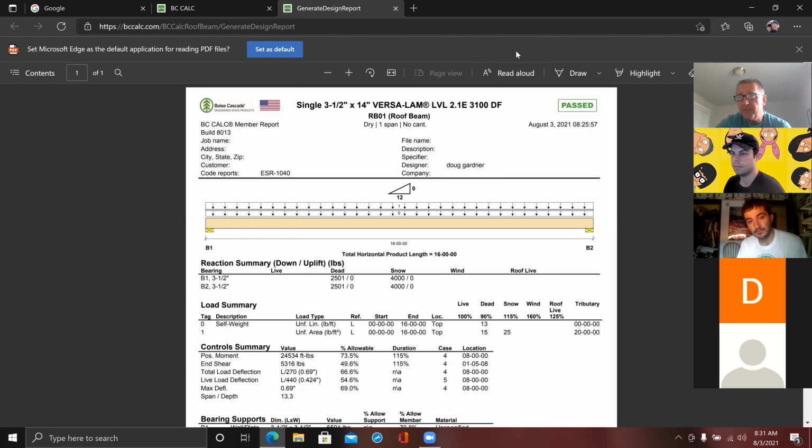By the way, flexibility is kind of important with respect to seismic stuff, isn't it? Don't you want things to bounce because then they won't break? It bent, but it didn't break. You actually want it to deflect so it won't fall down. So you build movement into it. It's kind of interesting. There's a lot of stuff to think about around this, but I feel like that would be the ultimate power move, just to tell your contractor, I don't want that to deflect half an inch, spec a bigger beam.